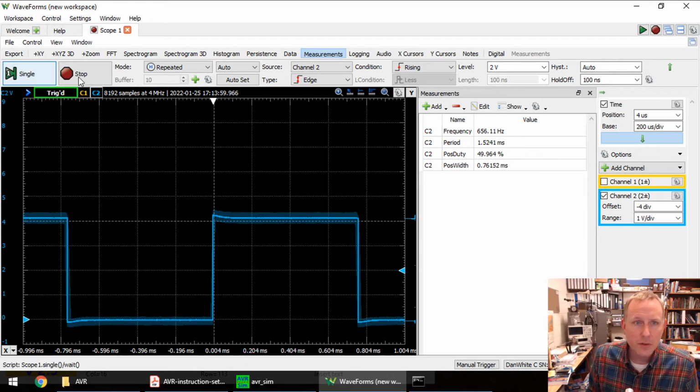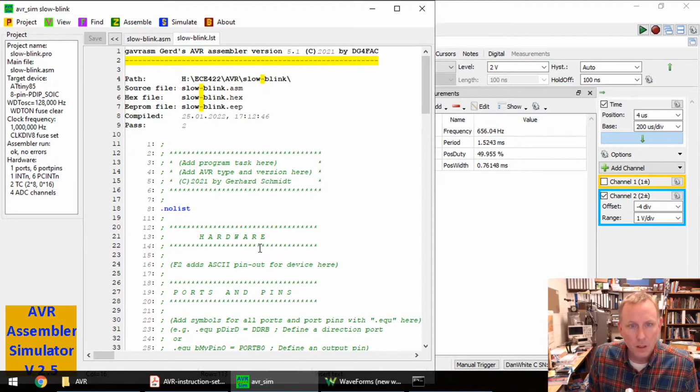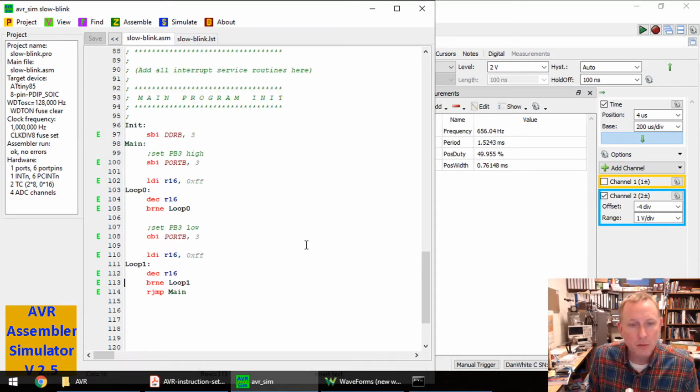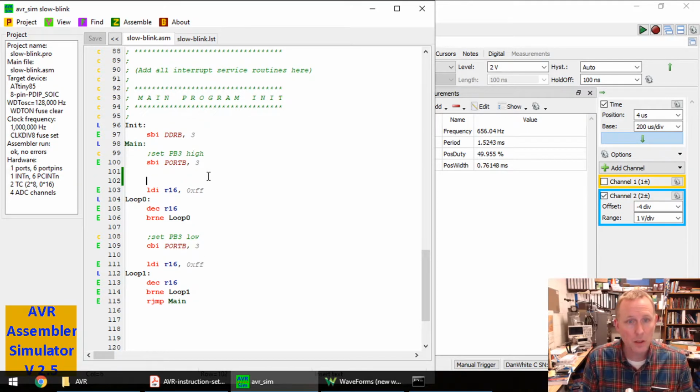All right, how do we slow this down even more? Well, the problem is our registers only hold 8 bits. We can only count down 8 bits. So maybe we have to count down and count down. Check it out. LDI register 17.